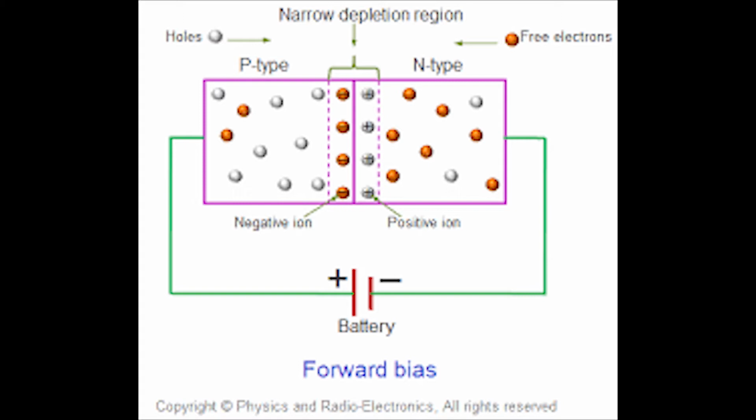Other than that, a diode can only allow current to flow in the forward direction when the forward applied voltage is more than the barrier potential, 0.7 volt for silicon or 0.3 volt for germanium. If the forward applied voltage increases from 0, the diode will start conducting only after this voltage reaches just above the barrier potential, or forward bias voltage of the junction.